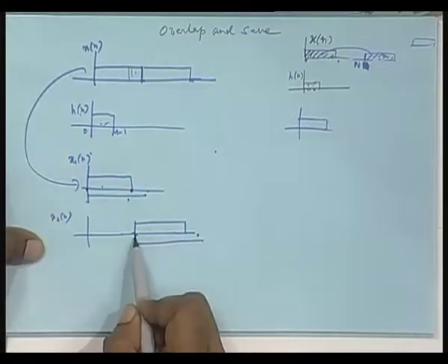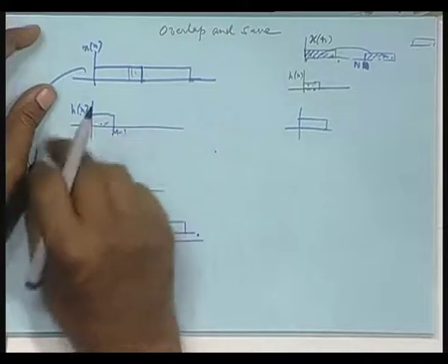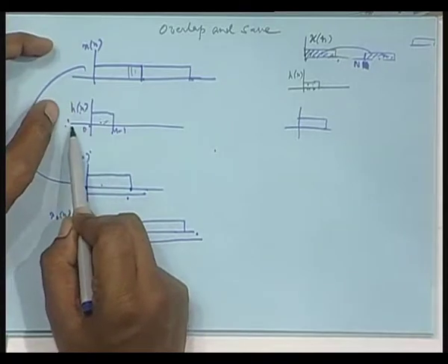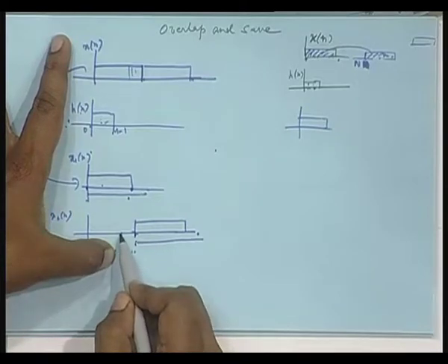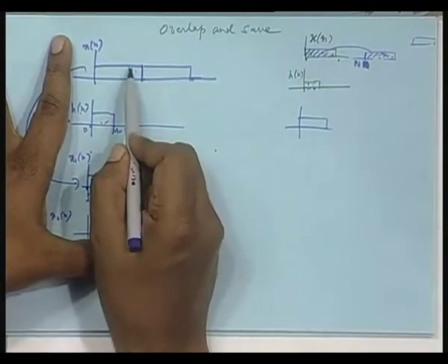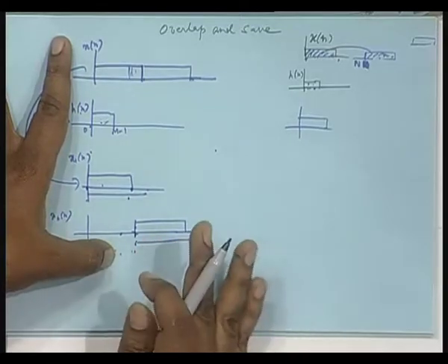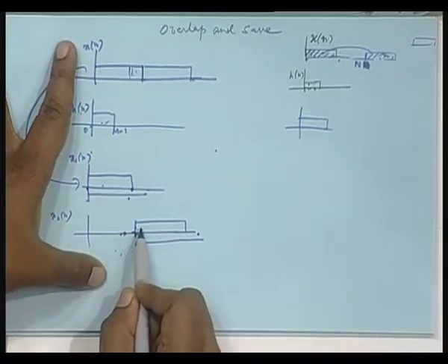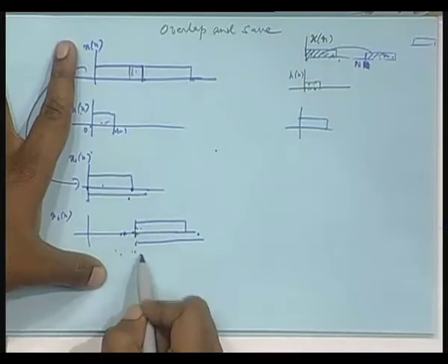That means if I do this convolution at this point, it will be wrong. If I reverse it, 0 to minus of M minus 1, that entire thing comes here. They multiply by 0 here and only one sample. So you get some result, but that is wrong, because in effect there was no 0, there was data, but you have made it 0 here. Fine, you understood there is something that is wrong. You go for the next one, still partly it will be 0 here and only two valid data are coming, so still that output will be wrong.